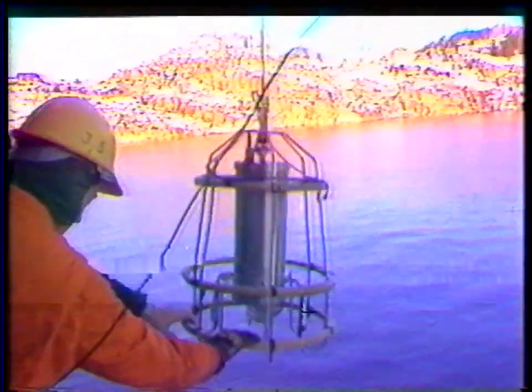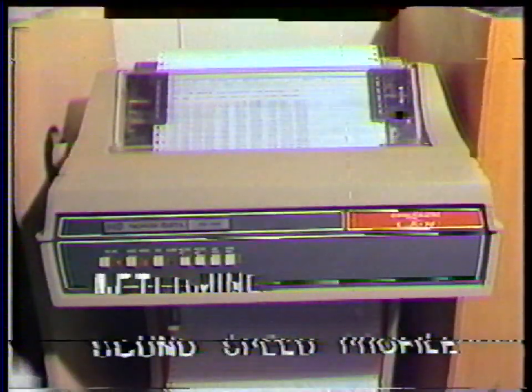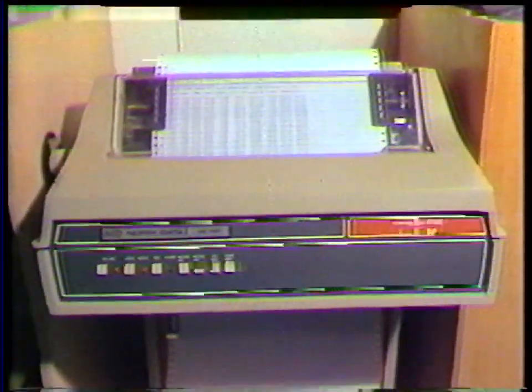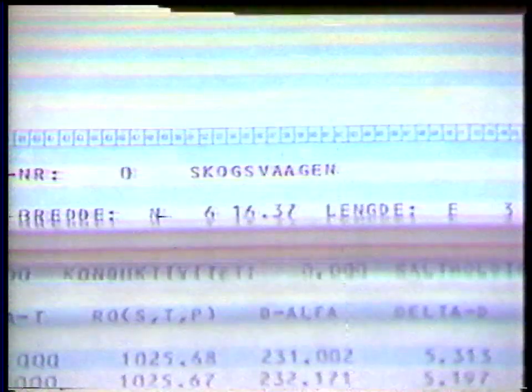The third task of the calibration is hydrography. While the ship is being anchored and rigged for the calibration, the hydrography can be performed. Use of a CTD sonde is convenient, for the temperature and salinity profiles can be logged automatically. The sound speed profiles and average sound speeds over possible depth intervals of sphere suspension can be computed. When the final depth is determined, detailed knowledge of the hydrography allows refinement of the nominal value of target strength.